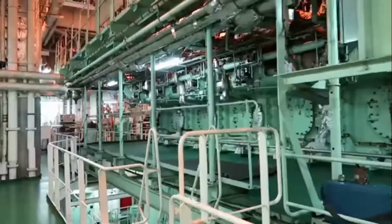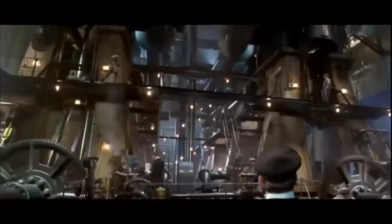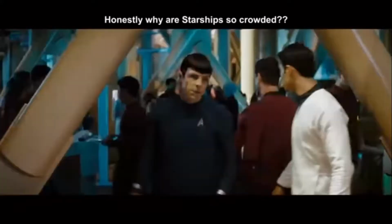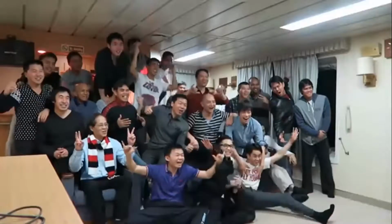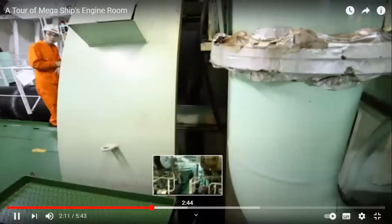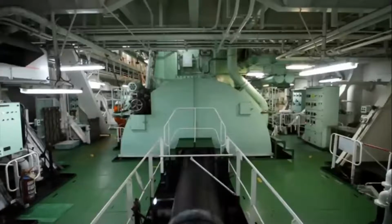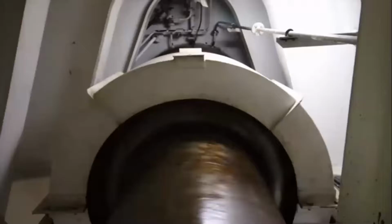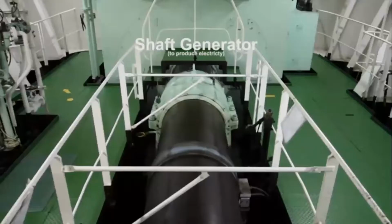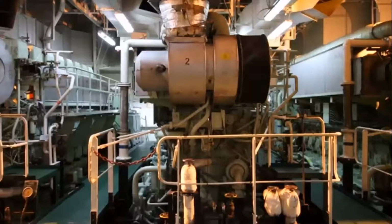You might be wondering, where's all the crew? Well, unlike the past or future, all cargo ships nowadays, except for passenger and military, are designed for minimum manning. We're talking about 20-something people here on a 400-meter ship. At the back is the flywheel. All that power is transferred to the propellers through the shaft. And the big block is what we call a shaft generator. At a high enough RPM, we won't even need to use the diesel generators at all to power the entire ship. Speaking of diesel generators, we've got 5 of them.